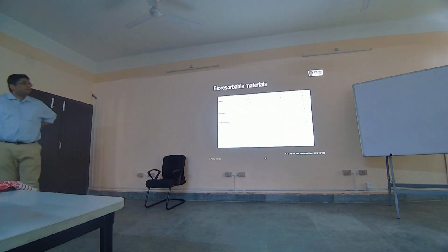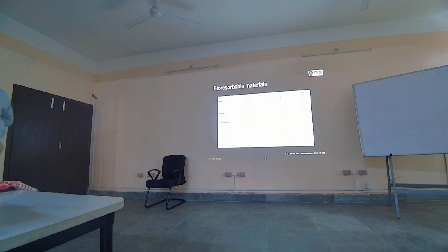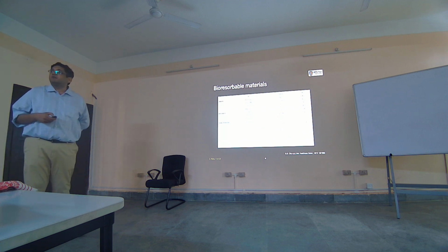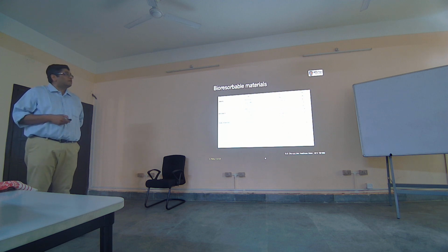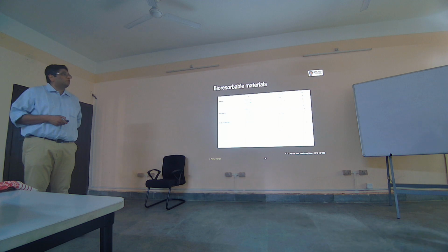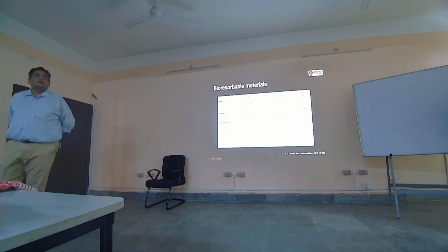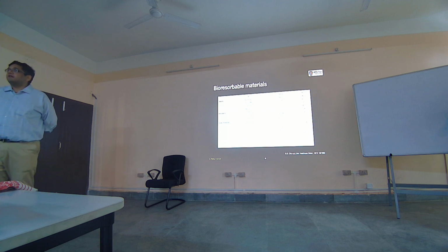So let's talk a little bit about bioresorbable materials. What are the materials one has to think about when one is working in this field, right? If you think about conductors, we have to move away from copper and aluminum because those are not bioresorbable. What are bioresorbable are magnesium and calcium, iron, zinc, molybdenum, tungsten. So you see that most of the electronics that has happened in this field, as shown in the next few slides, will use magnesium electrodes rather than copper or aluminum that we normally use.